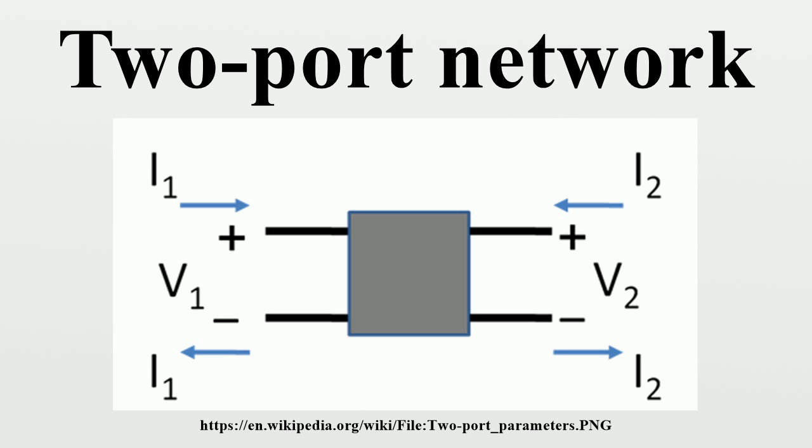Figure 4 shows the small signal circuit equivalent to Figure 3. Transistor Q1 is represented by its emitter resistance VT/IE, a simplification made possible because the dependent current source in the hybrid pi model for Q1 draws the same current as a resistor 1/gm connected across r pi. The second transistor Q2 is represented by its hybrid pi model. Table 1 below shows the Z parameter expressions that make the Z equivalent circuit of Figure 2 electrically equivalent to the small signal circuit of Figure 4.